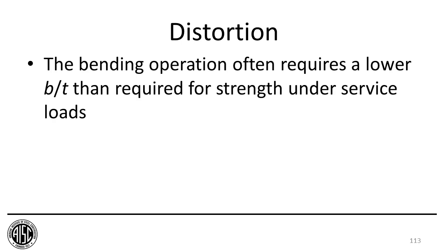And one final thing to note, and I'll say this again, I believe in the next presentation in session 2, is that the bending operation often requires a lower slenderness than required for strength under service loads. So once you get your member designed, for service loads, you may still have some work to do.